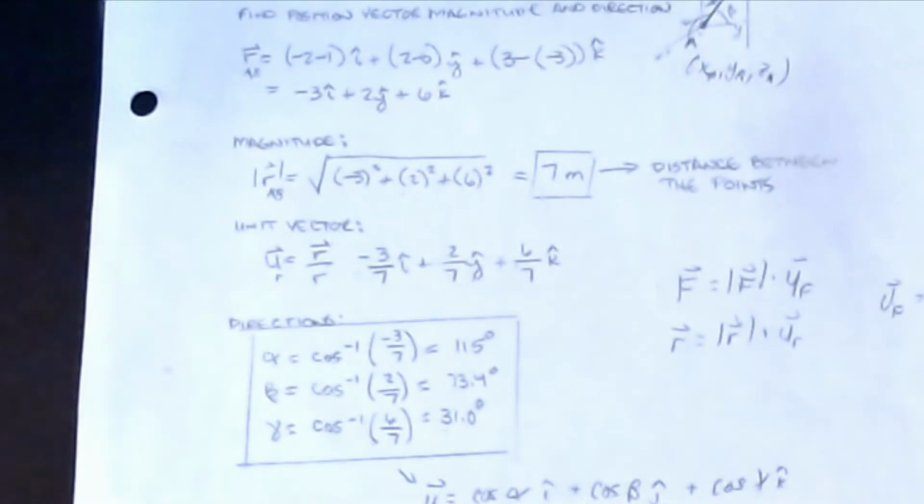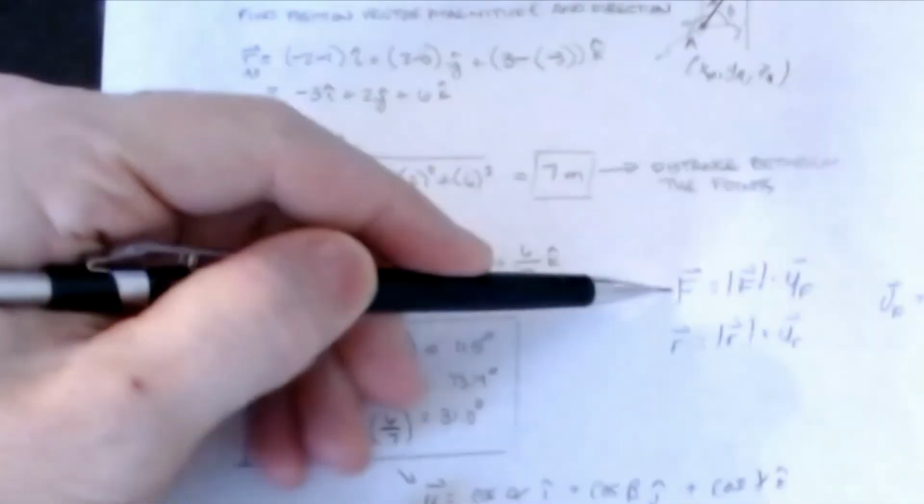All of this comes out of just simple, basic vector components and this idea of unit vectors, which are amazingly powerful in the things that we do. Unit vectors are used all over the place, even for things like velocities and accelerations. If I know the direction of the effect, I can create a unit vector to define that direction, and then all I do is take the magnitude of whatever it is, the magnitude of the velocity or the force or whatever, and I can really easily construct the full form vector of this. I can basically construct this guy, okay?